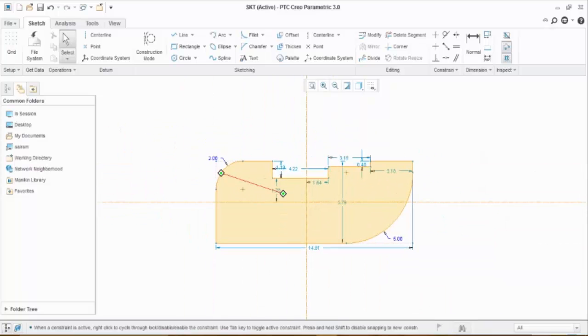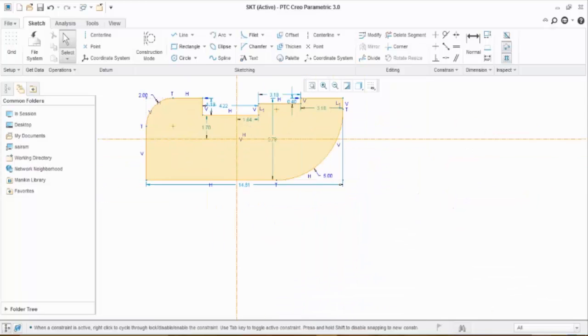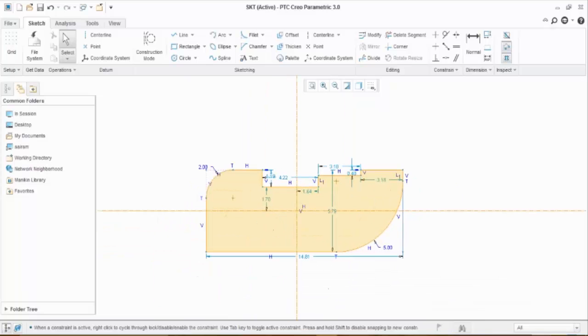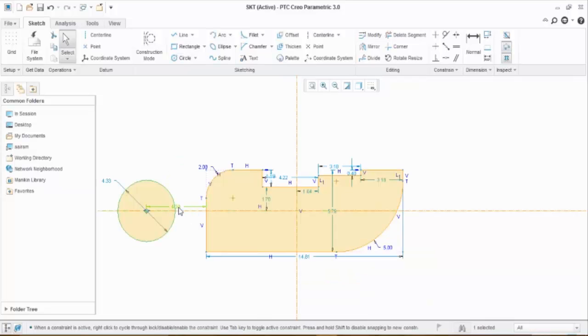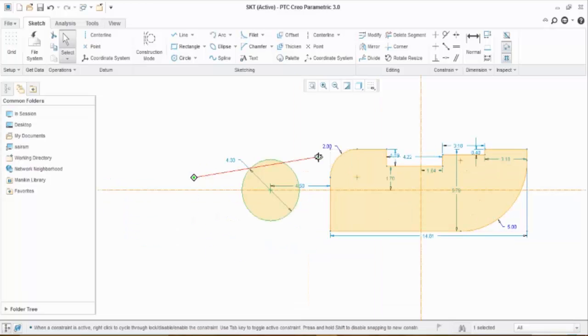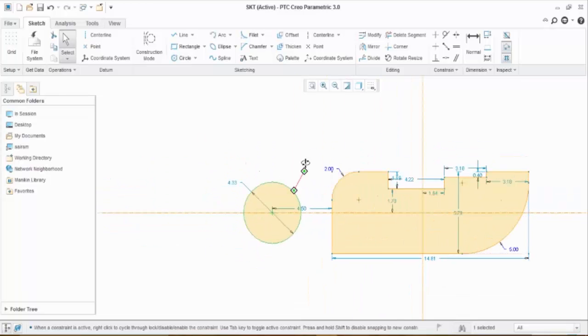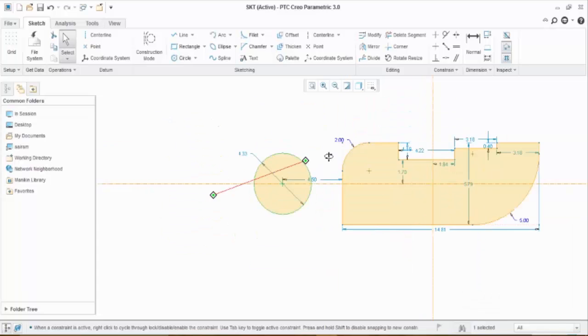We are panning it with the help of the middle button of the mouse. We are pressing it and panning. Panning only changes the screen. We are just manipulating the screen, not making any kind of move. If two components are here, here is a circle at a distance of 4.50, right? If we pan here, it will not change the distances, right?